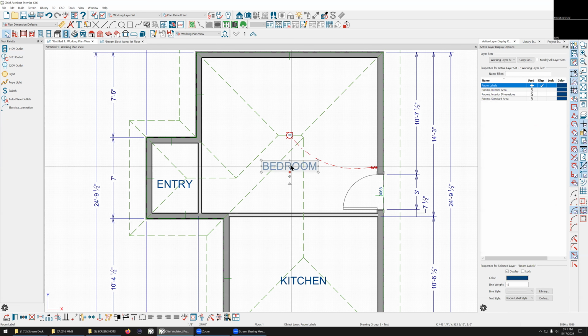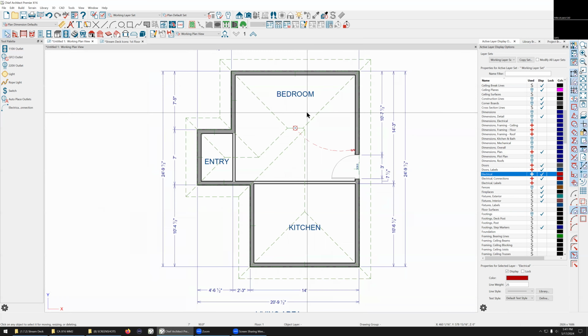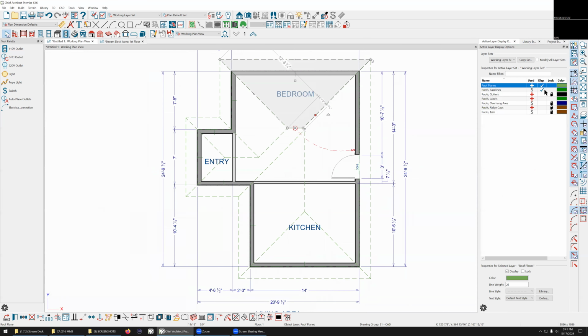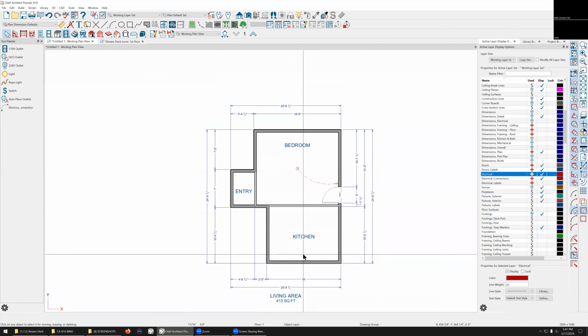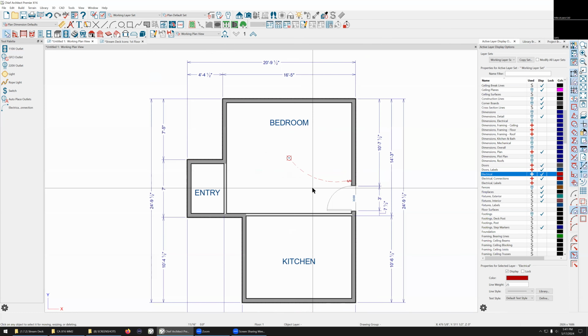And when you move the wall, the dimension is hinged to the wall, so you move it, it's going to get bigger or smaller. You didn't really have to go through and do an interior dimension line across the room. It's already there, no matter what size it is. It could be a closet, and you still have the dimensions.